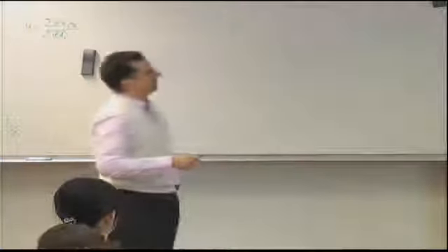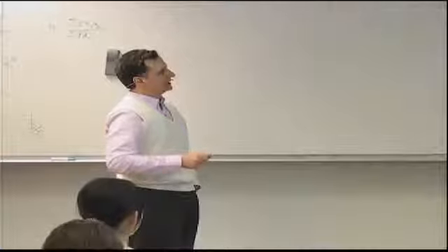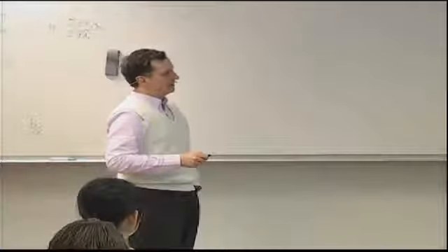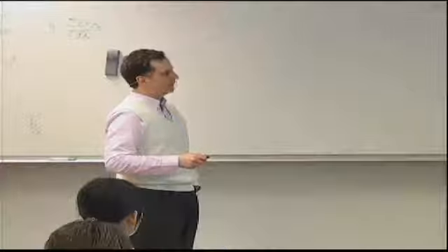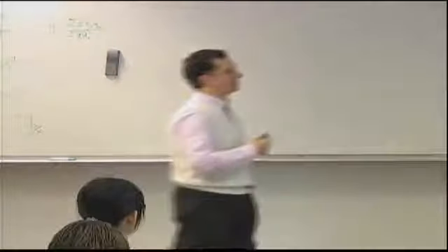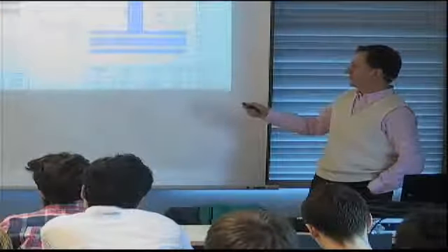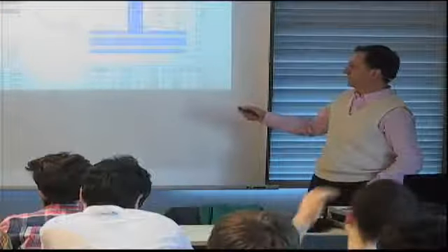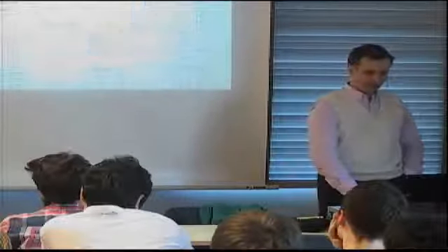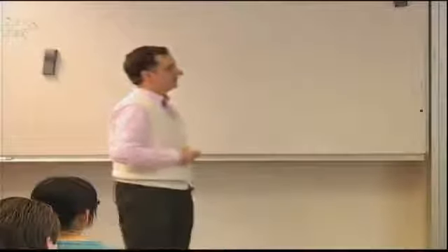And we know the buckling load then is given by this quantity. The D is the D matrix for the skin. The M is the number of half waves. The aspect ratio is the length divided by width of the portion between the stiffeners. It's not the aspect ratio of the entire plate, but it's the length divided by the width for each of these little bays created by the presence of the stiffeners. So the calculation says that the lowest buckling load occurs with 3 half waves along the length, M equals 3. This is the buckling load in newtons per millimeter.